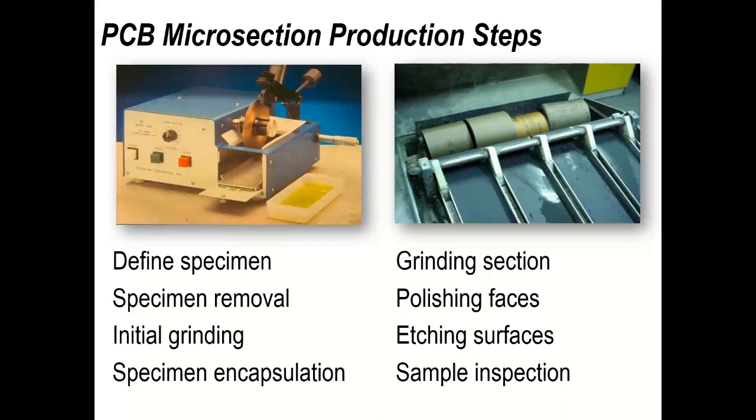The next step is grinding, and we use basically wet and dry paper, the similar sort of paper that you use when you're perhaps getting blemishes out of paintwork on a car or on a bike, a scooter or whatever, before a painting operation. And we're using different levels of paper. We're using water to lubricate that paper, but also to take away any residue from the sample.